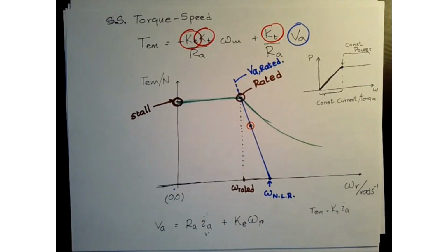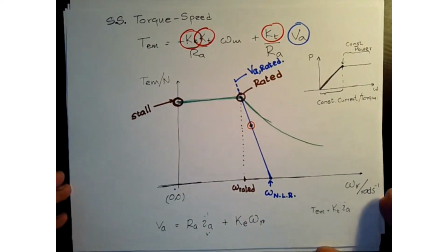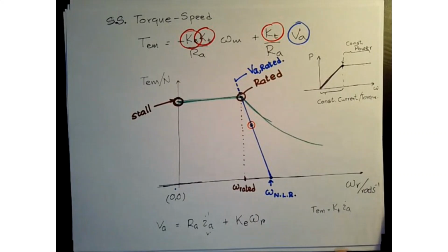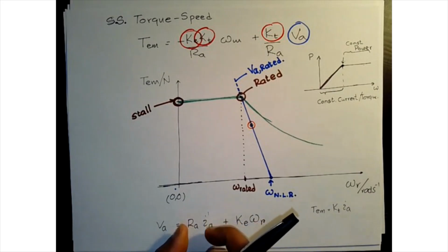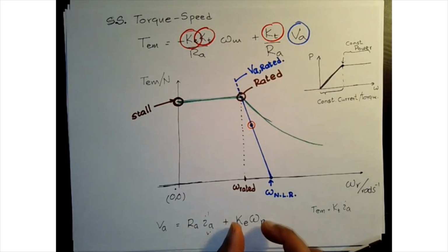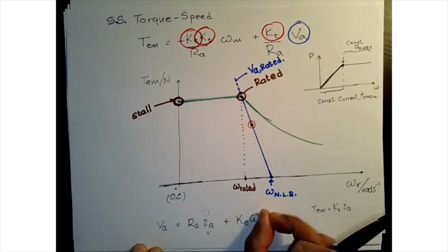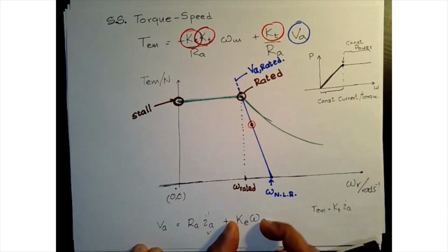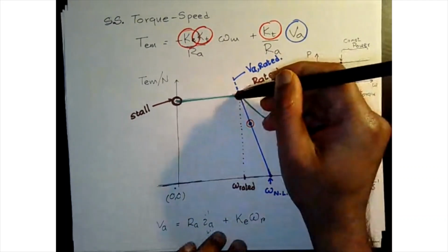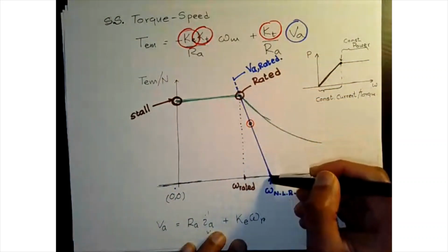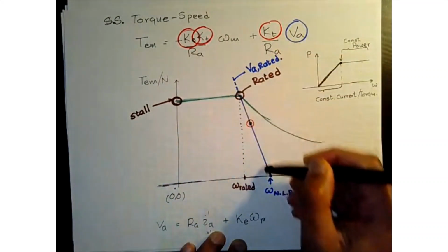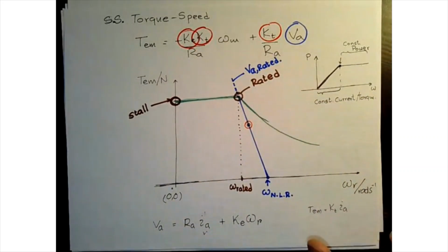That's the next step we want to properly understand. So we decrease current, therefore we reduce the voltage drop from the resistor, which means now we can go slightly higher speed, which builds up back EMF. But that's still traveling along this line. Fair enough?